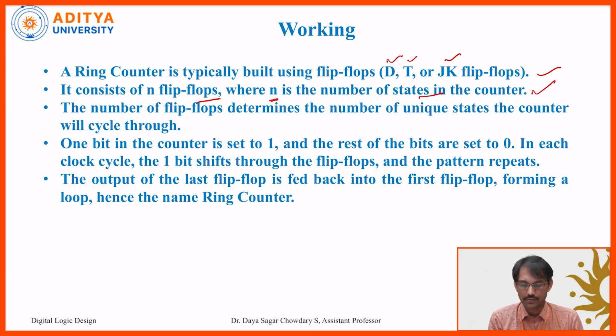The number of flip-flops determines the number of unique states the counter will cycle through, and one bit in the counter is set to 1, the rest of the bits are set to 0. In each clock cycle, the one bit shifts through the flip-flops and the pattern repeats. This we can discuss in the next slides.